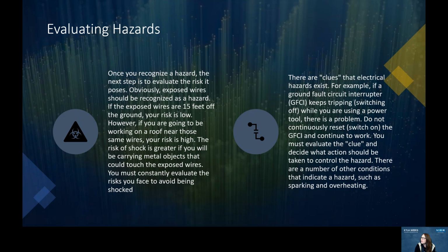You must constantly evaluate the risk you face to avoid being shocked. There are clues that electrical hazards exist. For example, if a ground fault circuit interrupter, or GFCI, keeps tripping, switching off, when you are using a power tool, there's a problem. Do not continuously reset or switch on the GFCI and continue to work. You must evaluate the clue and decide what action should be taken to control the hazard. There are a number of other conditions that indicate a hazard, such as sparking and overheating.